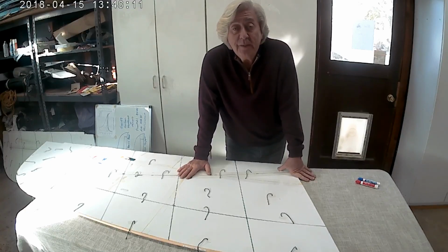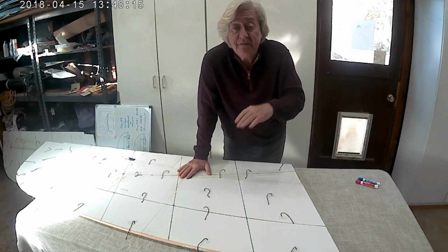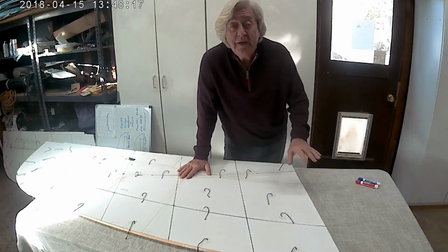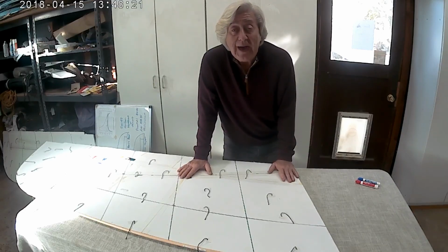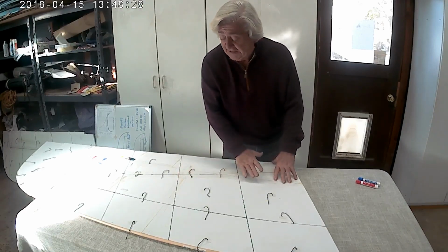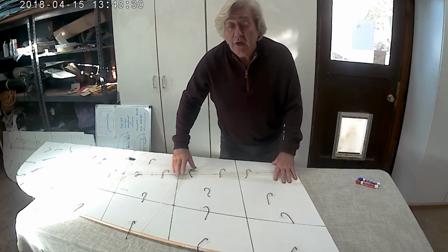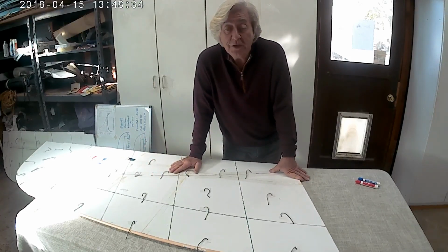You move the elevons up and down, you're changing the washout in the wing. And I have a whole series of 7 videos on the whole stall spin problem, and in there I actually physically show how the washout of the wing changes with different shapes of elevon. If it's tapered one way or a barn door or a reverse taper, they all have a different impact on the amount of washout in the wing.